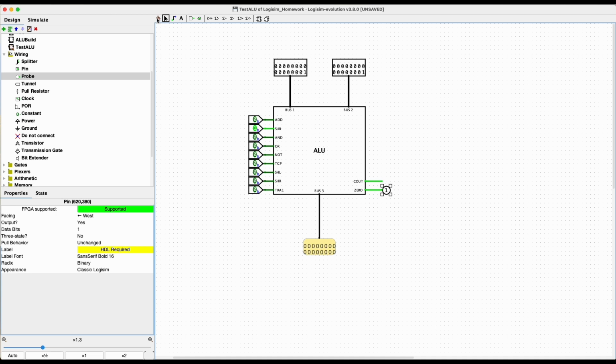And now let's do a shift right, and you can turn on these bits right here. And one thing you want to test with your shift right, make sure that this 1 bit, see how it gets copied to 2 spots right here. And you might want to check some other digits with shift right, and then shift left over here. And you can see that this bit comes 1 bit over, like the lowest bit gets shifted left up to there. Okay, and then add, well, let's go ahead and add 3